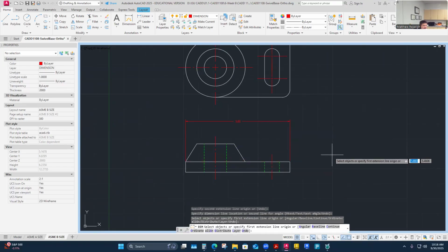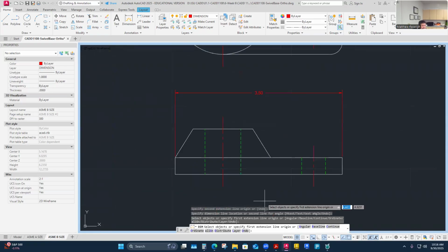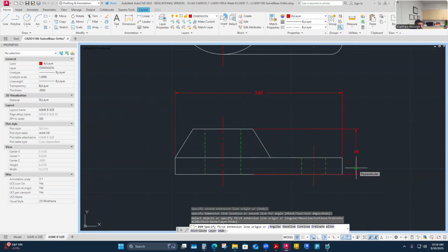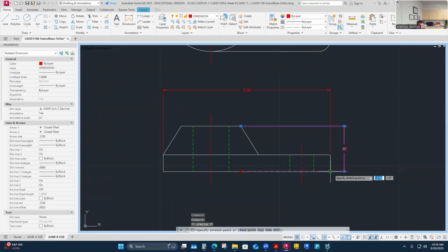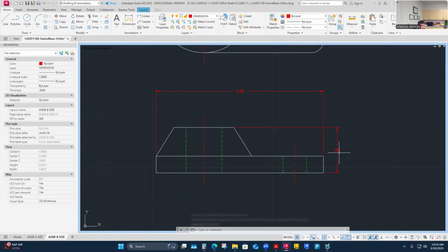Maybe it's a reference dimension in the future anyway. I just learned that sometimes those overall dimensions are really not a super powerful controlling dimension. They're more informative than they are super controlled. Maybe the heights are a better dimension. The overall height, because it is kind of controlled off the base, and bases are great datums, great control hold features, the way it sits flat on something. Yeah. So this one is a better control dimension than that one.